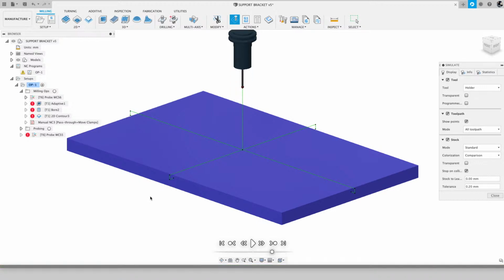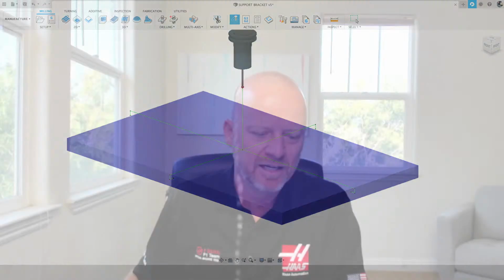Okay, so I see a comment from AL. So this is to compensate for missing alignment of the stock. And on machines that don't have a probe, you just have to align things yourself or manually. Yes, it'll be a manual operation, AL.